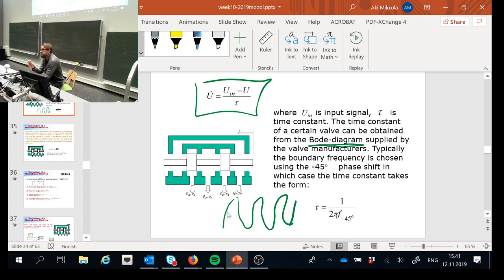That's what it is. And then you're monitoring how closely the spool axle position can follow that signal. And it can follow it fine, particularly when the frequency is low. But when the frequency is getting higher, the spool has more and more difficulty following that signal. And eventually it's going to lose the signal, such that the difference between the axle position and the signal becomes very large. And when the difference is going to be 45 degrees, we're going to look at an example in a second, then it's considered that it's no longer accurate.